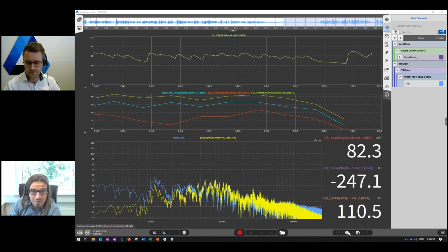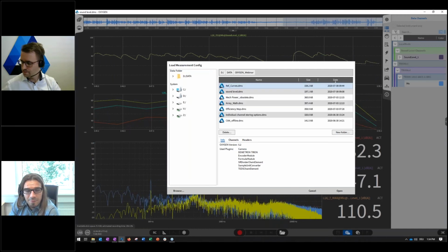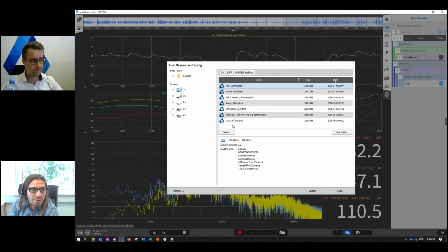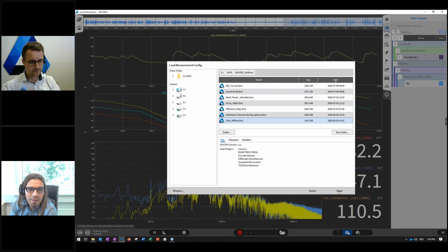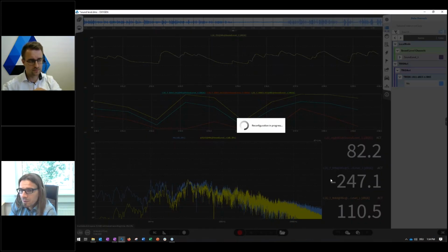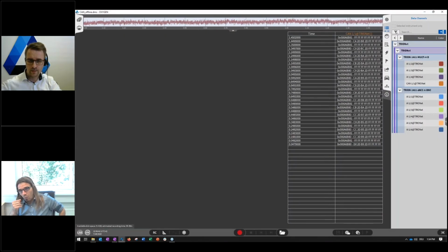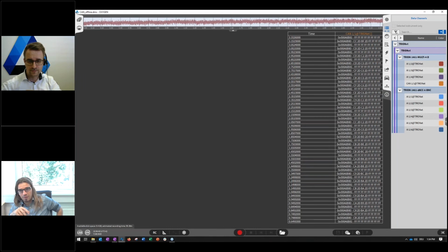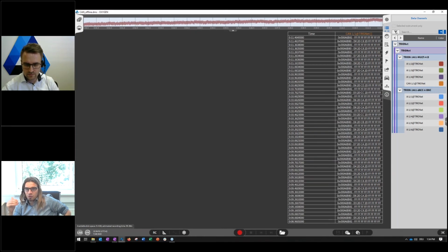In the past, or let me start like this, when you acquire, for example, CAN data streams or automotive bus data streams during the measurement, you don't necessarily know during the measurement which channel is important to you for the analysis. So you don't necessarily know which messages and which channels need to be decoded during the measurement.